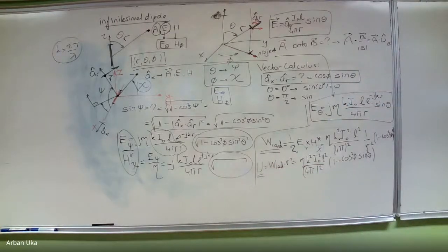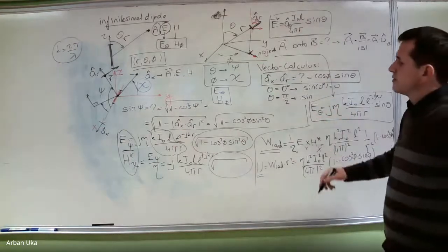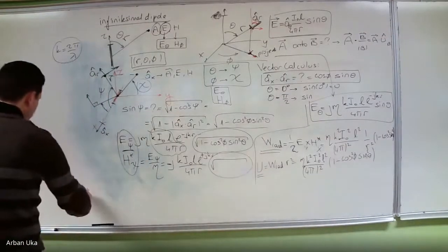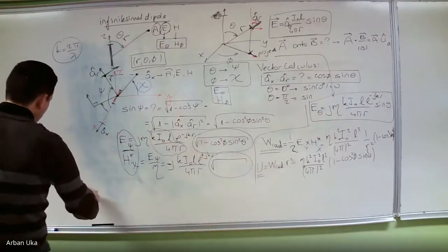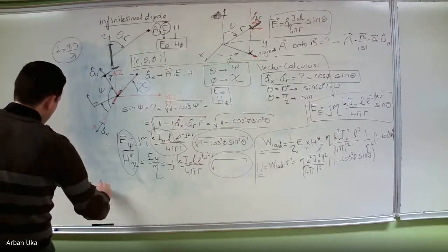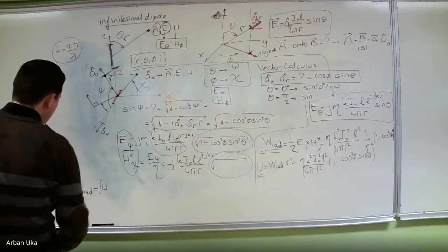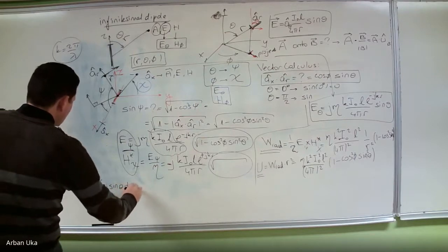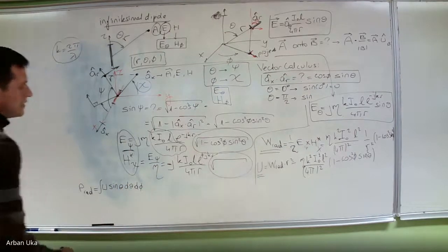From the radiation intensity, we can determine the total radiated power. This is going to be the integral of U sine theta d theta d phi.